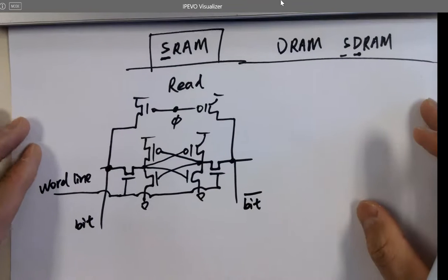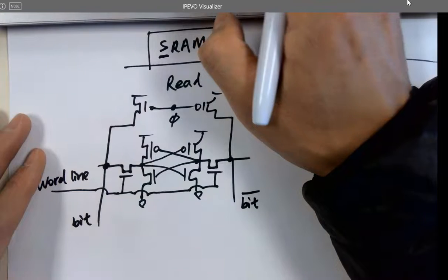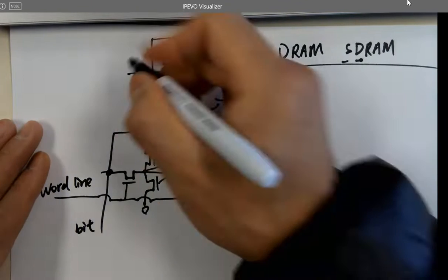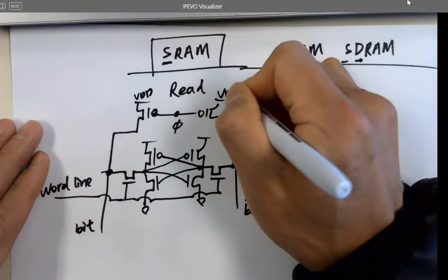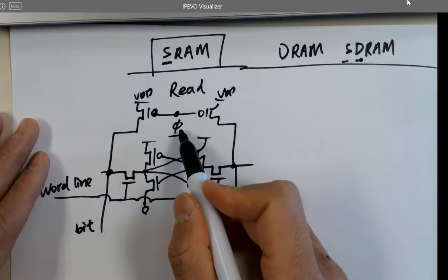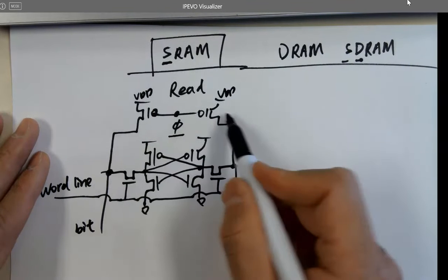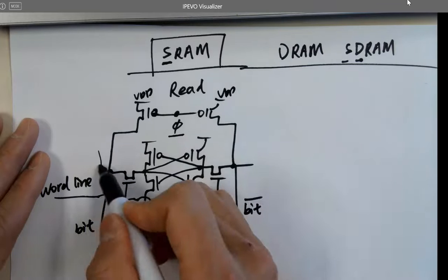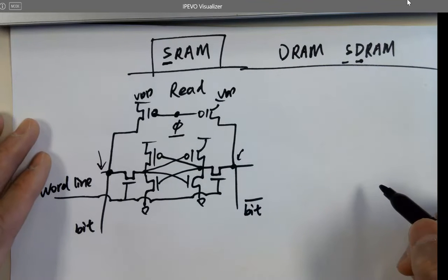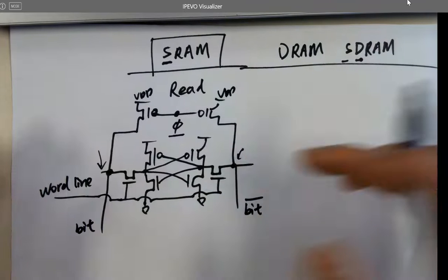Like I said last time on Wednesday, it pre-charges. It turns this on because these are VDDs. So it turns this on, which is you give a 0 to this signal, right? So you can turn on two PMOSes. That's going to flow charges to these points at the same time. It's going to charge them up to VDD. And then turn it off, so you can get two floating VDDs.